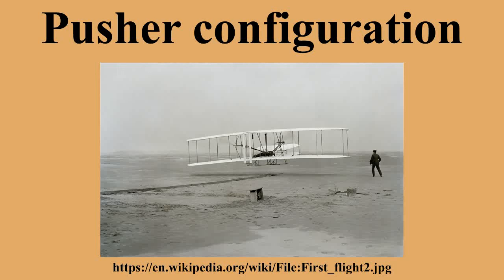In case of a crash or crash landing, fuel and oil in the aft engine area are less likely to be a fire hazard, and high-energy propeller fragments are less likely to enter the cabin area. At the time when many military aircraft were pushers, the engine afforded some rear protection to the pilot. A pusher ducted fan system offers a supplementary safety feature attributed to enclosing the rotating fan in the duct, therefore making it an attractive option for various advanced unmanned air vehicle configurations or for small, personal air vehicles or for aircraft models.